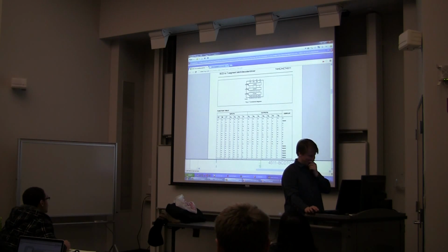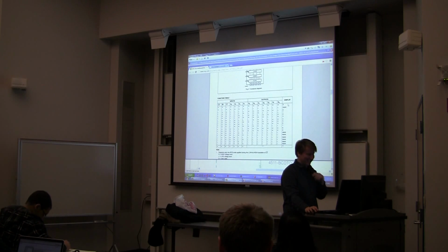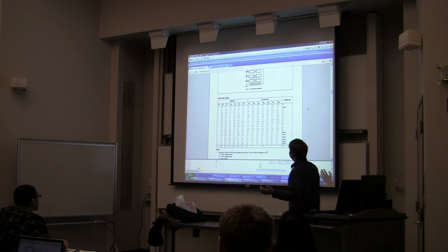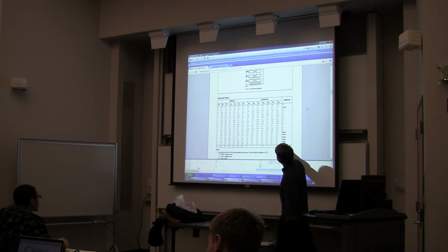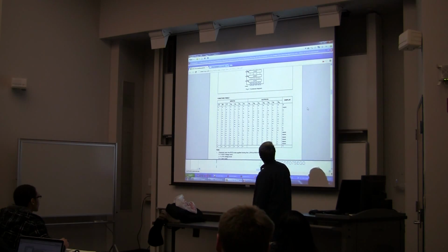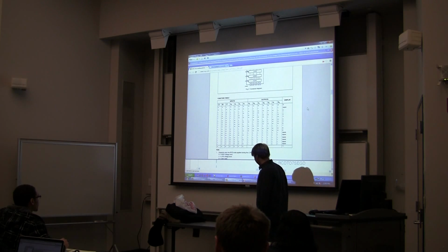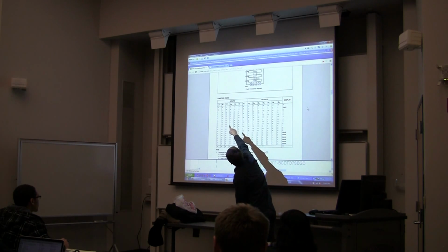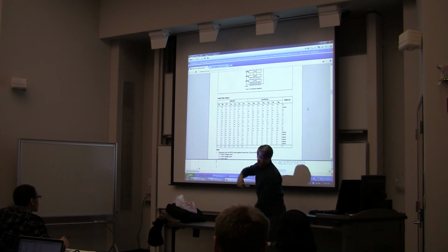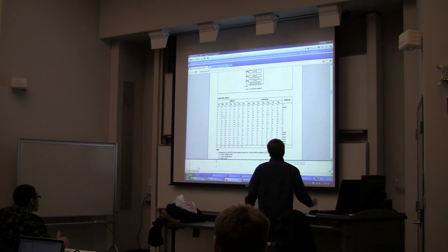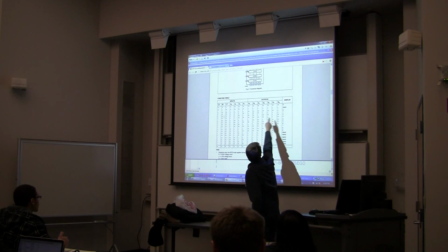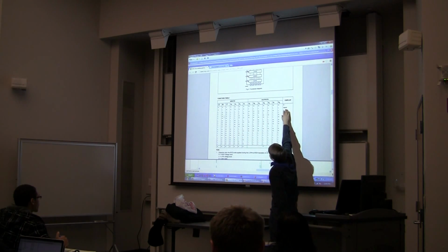So for those of you who are interested in electrical engineer sorts, they give you a helpful truth table. This is all possible things this thing can do. If it's making your eyes bleed to look at, you may not be an electrical engineer, and that's okay. But basically what it's saying is, if you have the blanking, it was BI, that was the ripple one, right? So if BI is high, the thing works. If it's low, nothing happens. The display is blank. Doesn't matter what everything else is doing. That's what the X is doing.